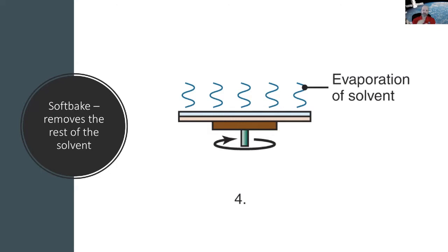And you also want to use as little material as possible because photoresist is very, very expensive. So you can get away with a lot of problems by just putting a lot of photoresist on the wafer and then spinning it. It becomes very uniform. But as you reduce the initial volume, it becomes more and more non-uniform when you're done. So our goal, of course, was to save money.